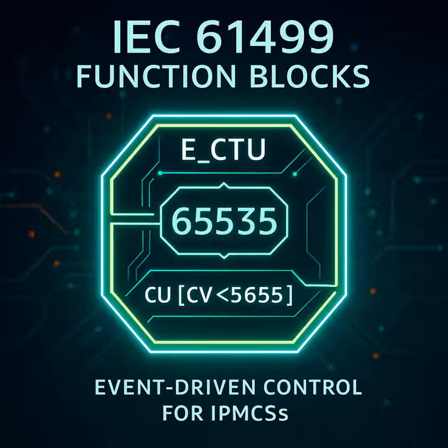The big advantage, especially in distributed systems, is that precision and reliability we touched on earlier. Your typical 61131 counter, like a CTU block, is synchronous. Meaning it runs as part of the PLC's scan cycle. Right. Its logic only gets executed once per scan.